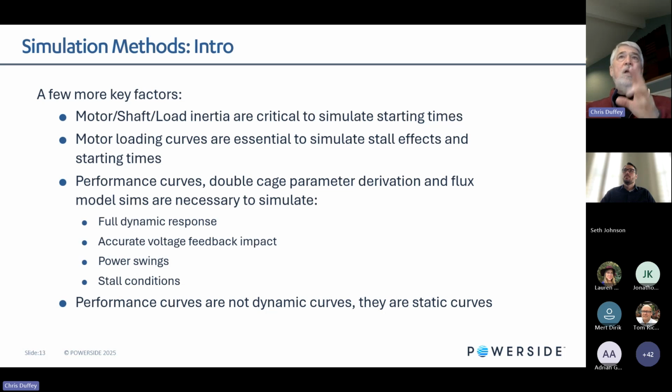Performance curves for double cage parameter derivations and flux models are necessary when you're going to do those. And in those simulations, you're going to simulate full dynamic response. You want accurate voltage feedback impact and power swings to be seen, and stall conditions to be seen. You're going to up your simulation detail, and so you're going to need more information. You're going to need the performance curves. You're going to have to do some derivations to get parameters.